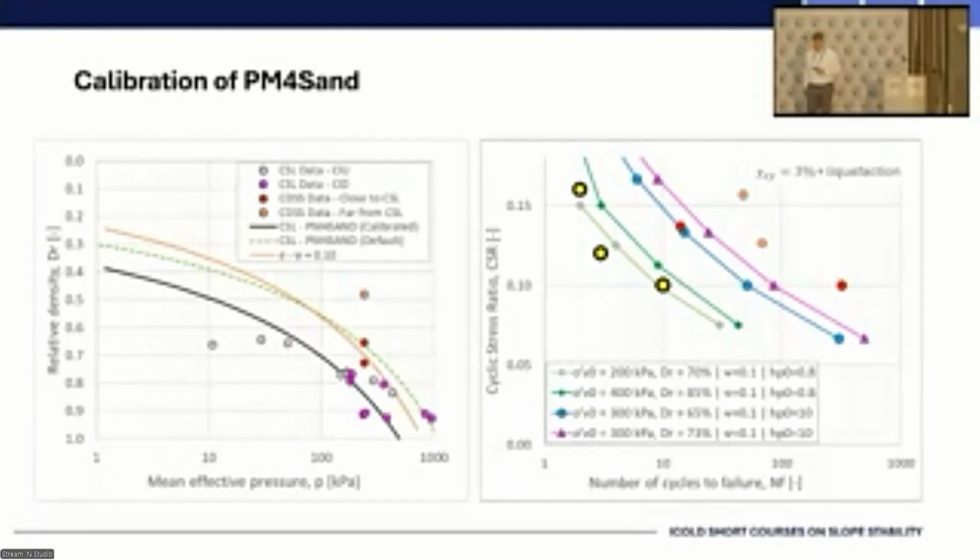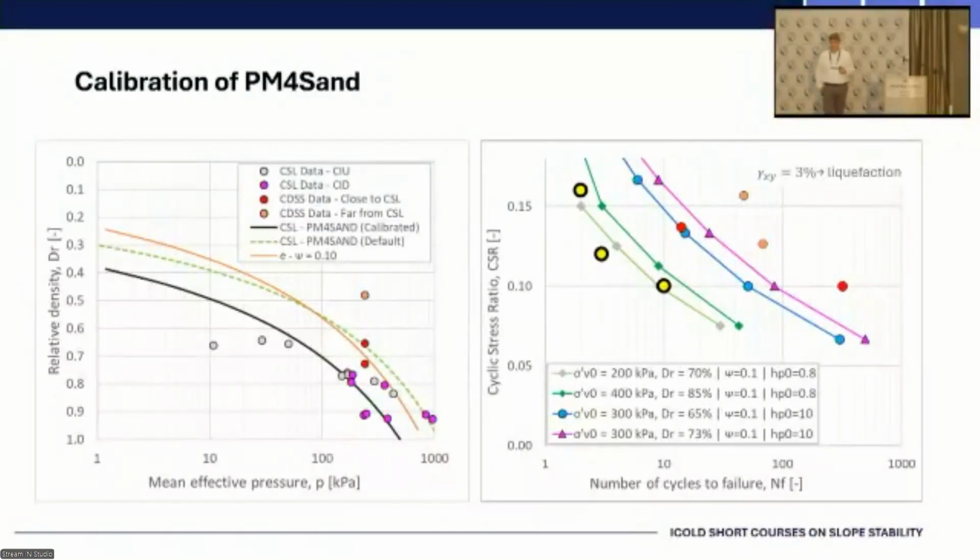So it's the solid black line, which is, I would say, compared to the data that is there, maybe closer. And then the best fit following that black curve that we could find is a state parameter of about, and there is sensitivity analysis around this, of about plus 0.10, which is the yellow solid line there, going more or less among all the data points.